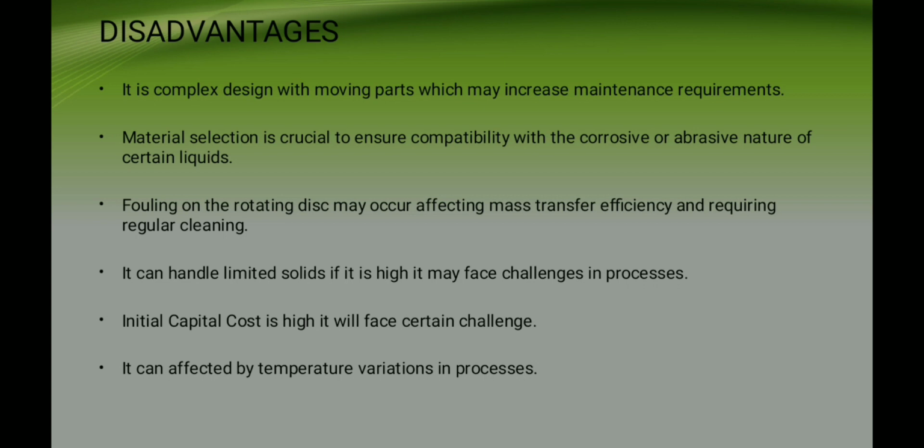Next, it can handle only limited solids. If the solid content is high, it may face some challenges in processing. Due to its complex design, it handles a limited amount of solids. If it is high, it may face challenges in the rotation of the impeller or in the inlet or outlet. And next, the last point, it can be affected by temperature variation in a process.